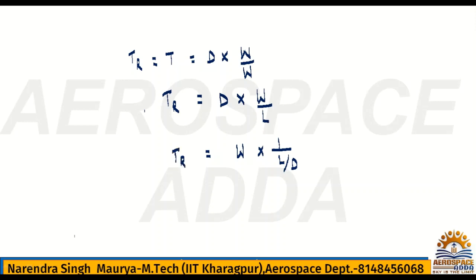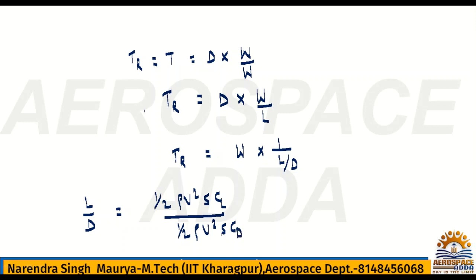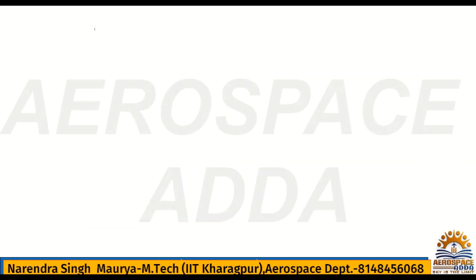This is nothing but thrust required. What is L by D? L by D is nothing but half rho v square S into CL divided by half rho v square S into CD. CL and CD are the lift coefficient and drag coefficient. We can write this for the constant angle of attack. Yes or no? So this value will be CL by CD. So here also we can write weight into 1 upon CL by CD. We can write this. So we have this thrust required.